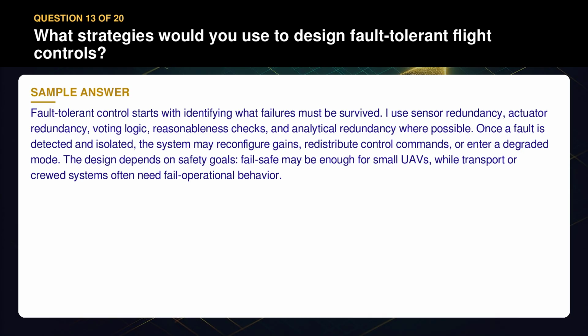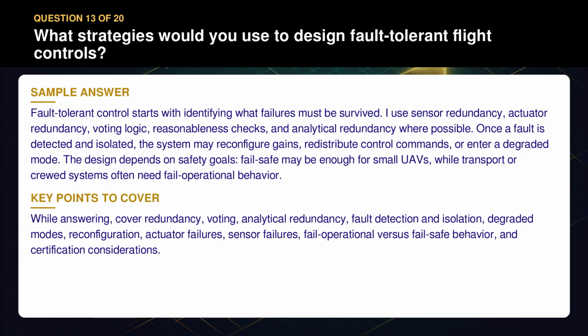The design depends on safety goals. Fail-safe may be enough for small UAVs, while transport or crewed systems often need fail operational behavior. While answering, cover redundancy, voting, analytical redundancy, fault detection and isolation, degraded modes, reconfiguration, actuator failures, sensor failures, fail operational versus fail-safe behavior, and certification considerations.